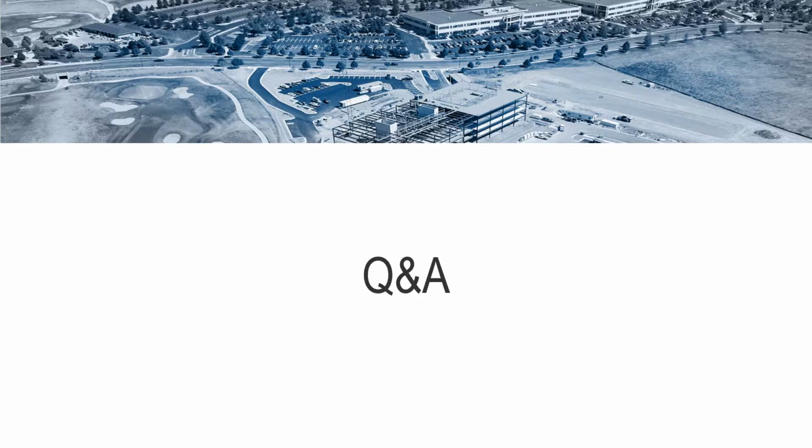So if I'm close to the objects, I don't need to slow it down, because I'm going to get a lot of information that's close to it. In a mechanical room, I will typically only do a low scan. And if I'm doing 30 of them, they're usually about 2.5 minutes with color, so it's actually capturing the photos. But I'm doing 2.5 minute scans, and if I'm doing 30 of them, you can see I'm probably going to be there for a little over an hour to 2.